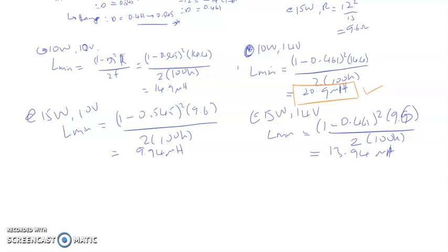So for this value that we have calculated, 20.94 microhenry times 1.25, because we need to increase by another 25%, we shall get 26 microhenry as the inductor value to be assigned in our circuit. This is just the initial value of 26 microhenry.